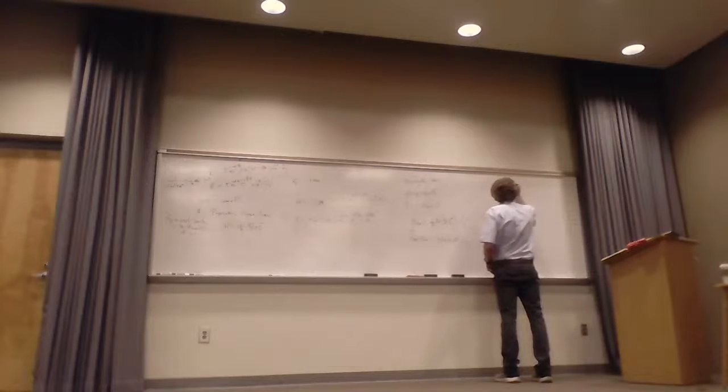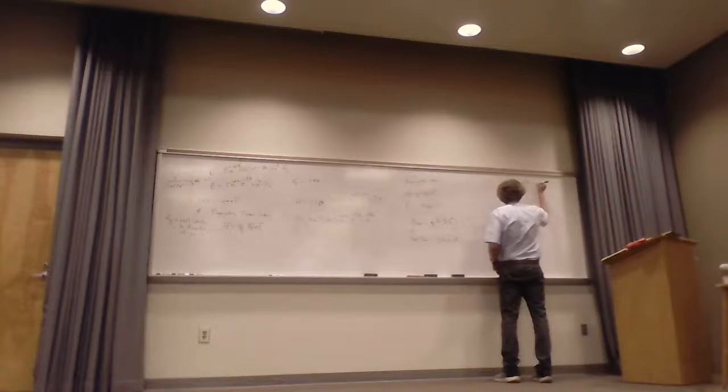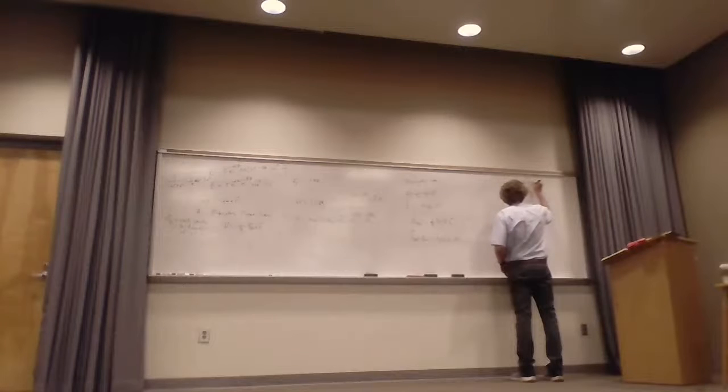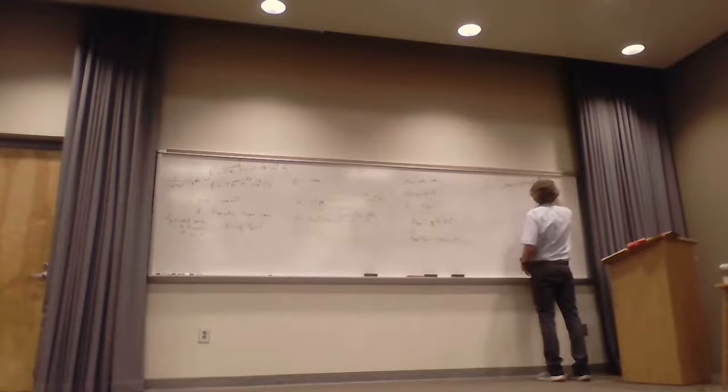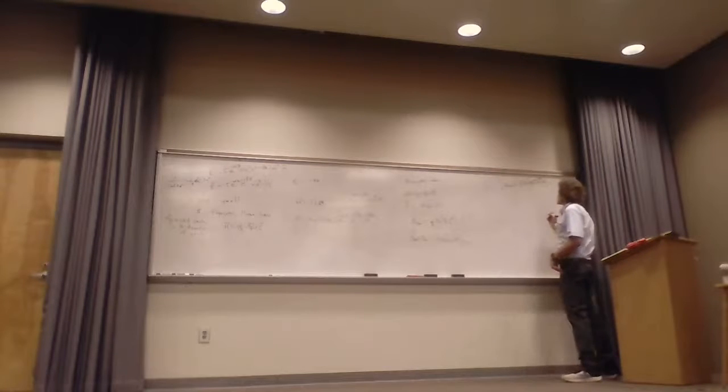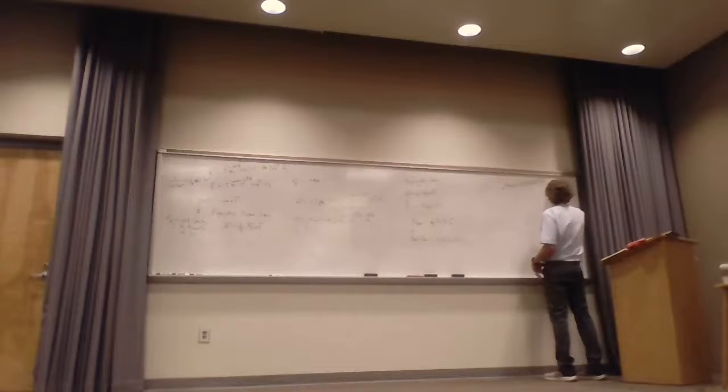So if we take a look at this, I'm going to write this down. I can say P av here is equal to 1/2 the real part. Well, E, I'm just going to say it's going to be some E naught e to the minus alpha Z, e to the minus j beta Z. And I'm going to go ahead and call it in the AX direction. We'll assume the wave is propagating in the plus Z direction and it's oriented in the X direction. I can't make it more general, but you can adapt this, you'll see how. Then you have to take this and cross it, that's cross product, with a conjugate of H.